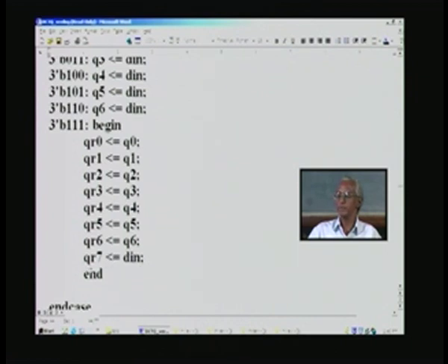These partial products which we have written, if they continue to be in the same Q0 register, then with the arrival of the next clock, that is the 9th clock, this Q0 will be overwritten. So, the partial product will get lost. In order to avoid this, remember that we need the partial product for the computation of the next stage, for which you need a further 8 clock cycles. That means this partial product will have to be stable for the next 8 clock cycles.